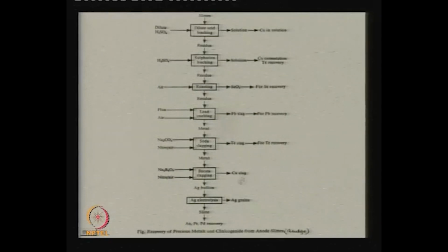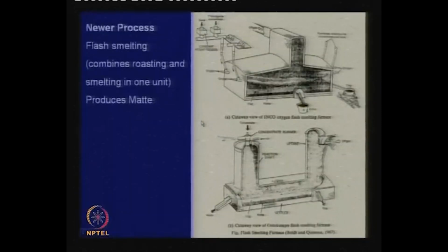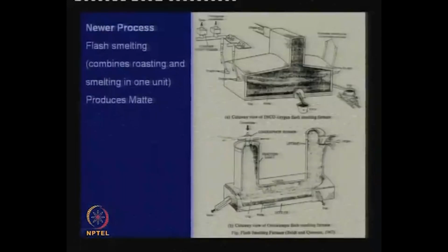We get silver, we get tellurium recovery, we can get lead, we can get selenium. These are all very standard steps that have evolved over centuries of trial and error. Of greater interest in copper metallurgy is how we are combining reverberatory, smelting, converting, and before that roasting all in one continuous copper making process.